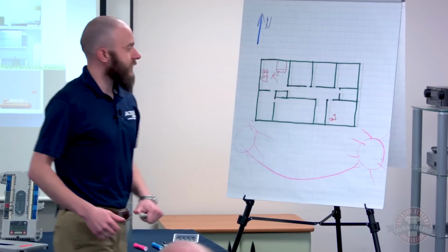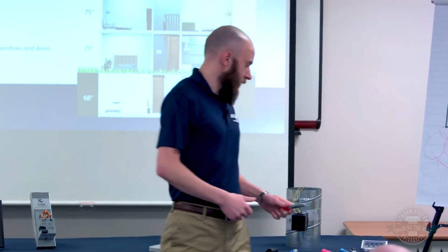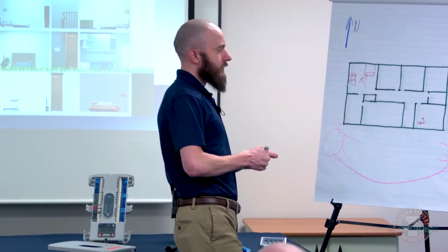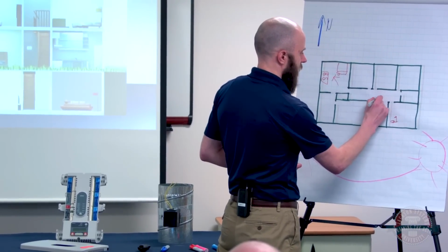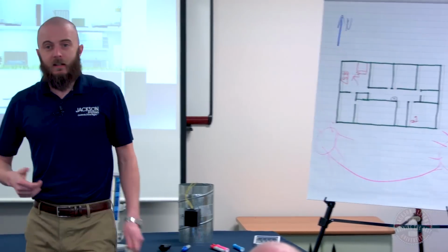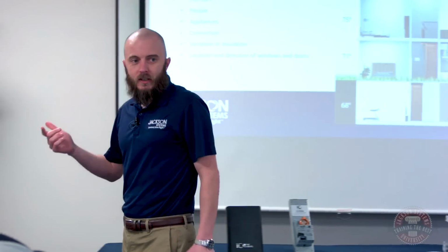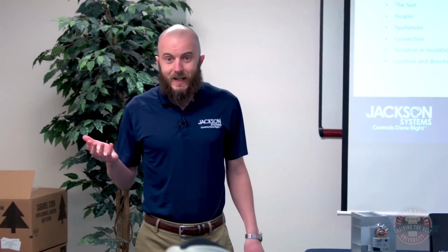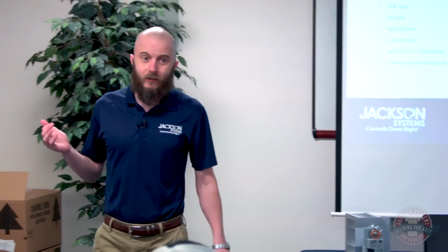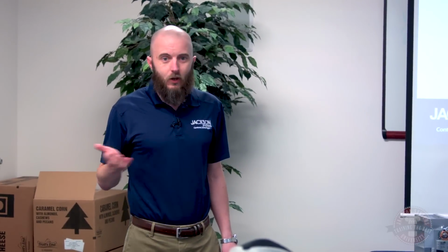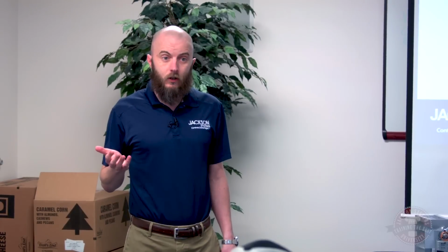Oh, and in this example here, a lot of times, where are you probably going to find the thermostat in the house? Pretty good chance it's going to be right here in the middle of the house somewhere in the hallway. So remember I mentioned that the thermostat, or where the thermostat's sensing from, is the only place you can really be sure is going to be comfortable in the house. Well, if we put our thermostat in the hallway like that, yeah, it's in the middle of the house away from windows and whatnot. But if that's the only place we can be sure that's comfortable, I don't know a whole lot of people that spend a whole lot of time hanging out in their hallway, right?